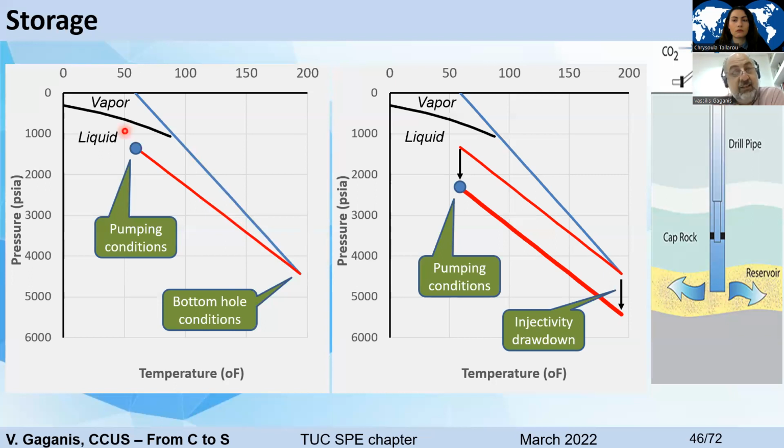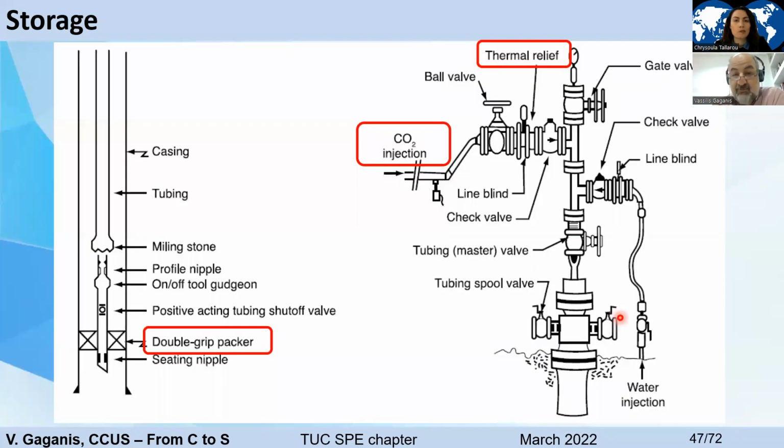Simply speaking, instead of using the line of pressure that was devised before, we need to shift it lower so that we establish an extra drawdown in order to make sure that CO2 will be able to flow in the reservoir. So can you see how things are getting worse and worse? I mean, we started with a pressure of 4.5 thousand, and we ended up with another, say, 1,000 psi more. So you need more compressors, more energy, more capex. It can be even worse.